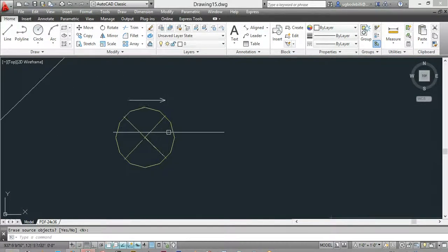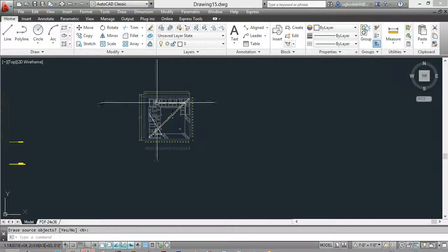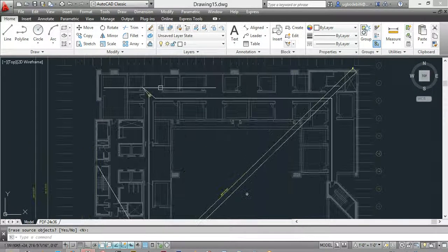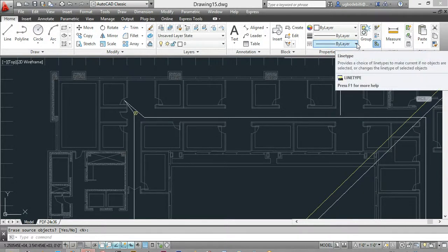Alright. So the next part of the assignment would be to create the partitions, the fire rated partitions that make the hallway a safe means of egress. And the type of fire rated wall you use is going to depend on the construction type.